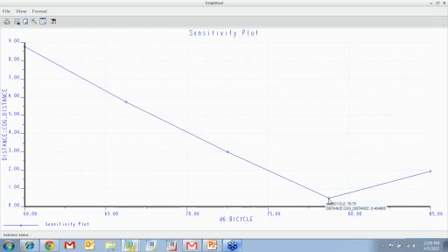Now, why is the center of gravity very important? The reason it is important is that if I run an optimization, say I want to optimize this value such that the distance is almost 0, and if I choose a range from say 60 to 70, I would never get that value, because the value that we want is around this range. So by running a sensitivity study, I am able to figure out, one, should I use this design variable in my optimization?